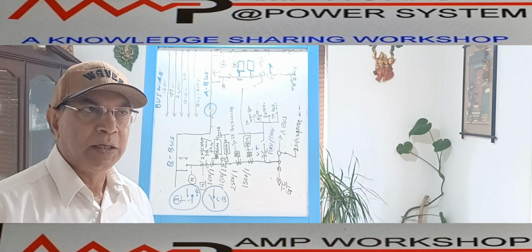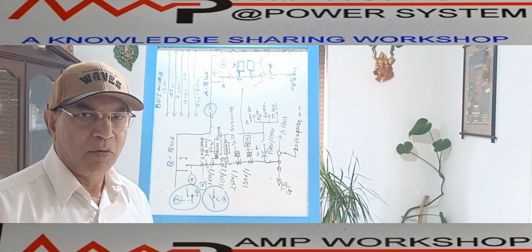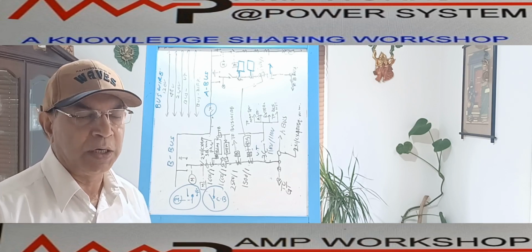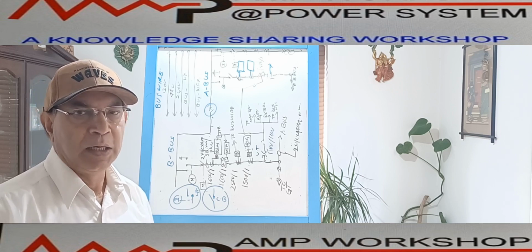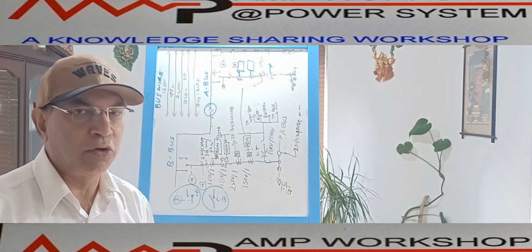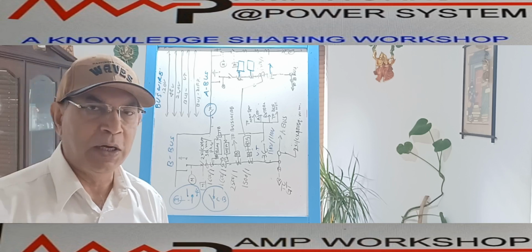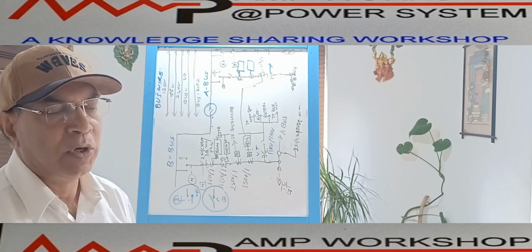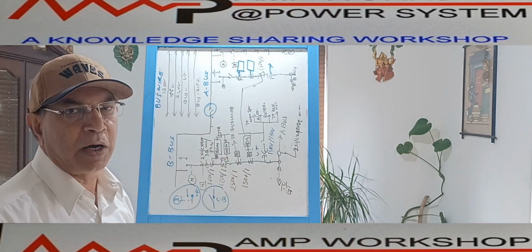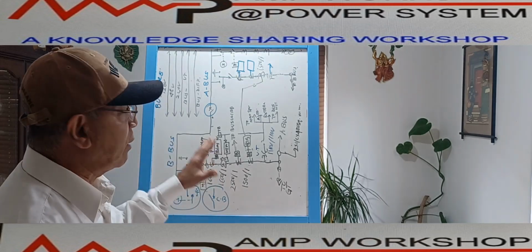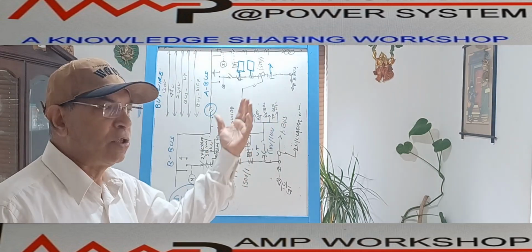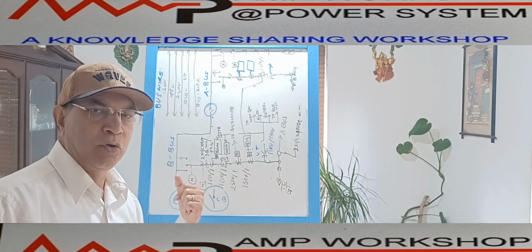Then I will show another single line diagram for the feeder which is supplied by one feeder only, like a transformer feeder or motor feeder, and that will be copied for all the panels or all the feeders, all the equipment in the plant. So this total thing is to be developed in one drawing only. That's why it is called overall single line diagram for 11 kV switchgear. As I don't have enough space, typically I will be showing one by one. But keep in mind that all the feeders are to be shown: whichever are connected to the A bus will be shown on the A bus, and whichever are connected to the B bus will be shown on the B bus.